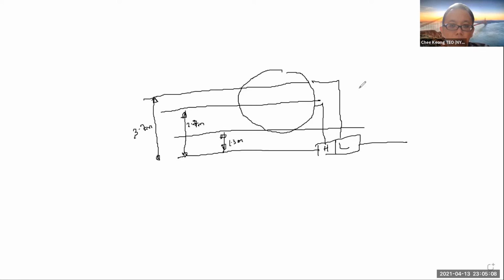Now, of course, in terms of the density, you have rho g here. This part here is the liquid, and this part here is the liquid, right? And then this is the gas. So rho g is your gas. Rho g is given by 1.25. And then, of course, there is rho FL, which is the rho fluid. Rho fluid is given by 930. And of course, there's another rho V here, which is the reference leg. They fill it with another fluid. Rho V is given by 1.25 again.